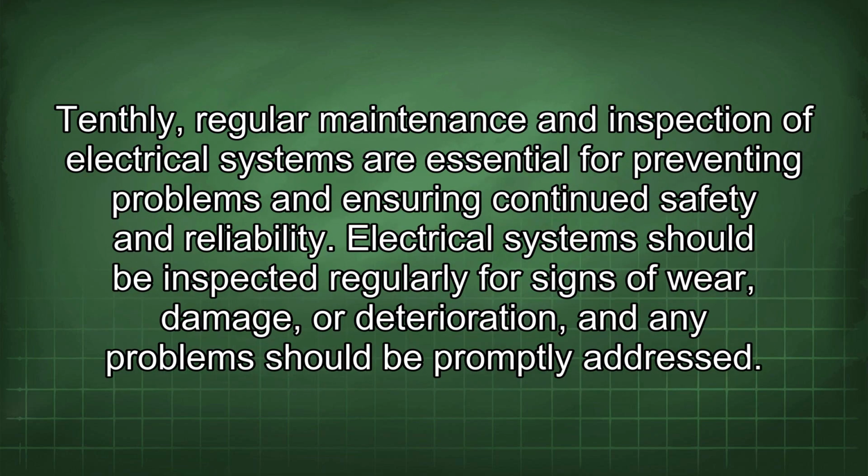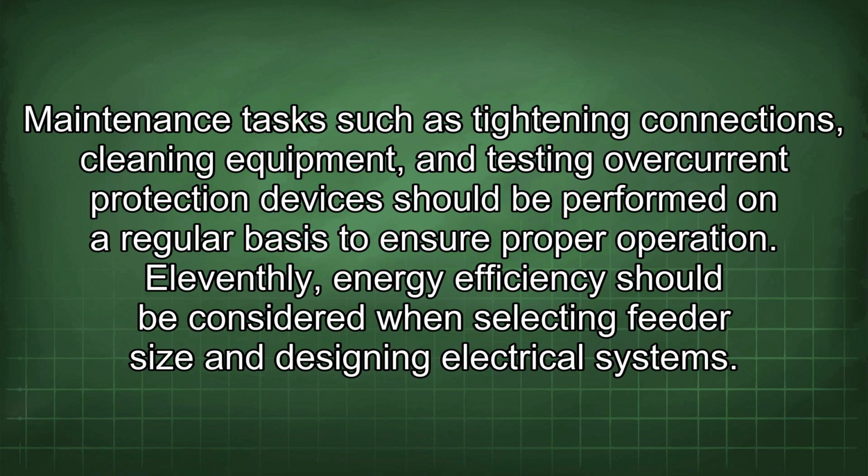Tenthly, regular maintenance and inspection of electrical systems are essential for preventing problems and ensuring continued safety and reliability. The electrical systems should be inspected regularly for signs of wear, damage, or deterioration, and any problems should be promptly addressed. Maintenance tasks such as tightening connections, cleaning equipment, and testing overcurrent protection devices should be performed on a regular basis to ensure proper operation.